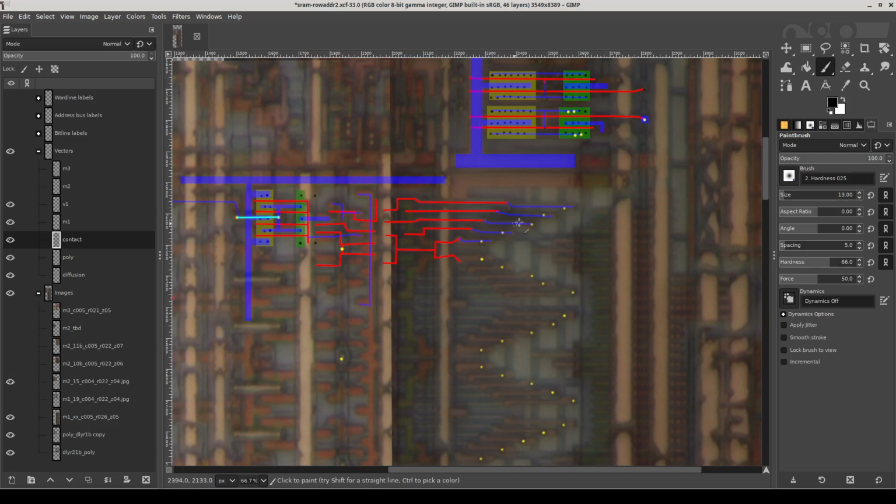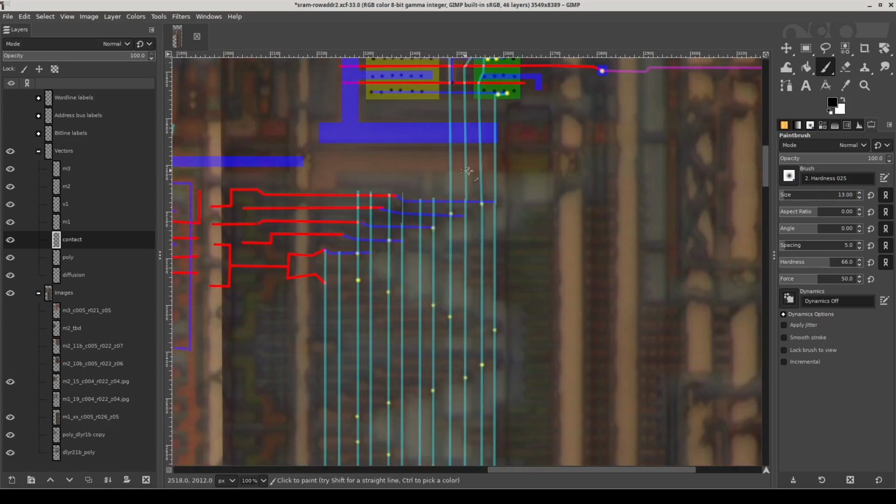We're not just going to be feeding in the raw address bus to here and then having a hardwired is equal to 0, is equal to 1, is equal to 2 circuit, because that would take up too much space. And of course, these vias are in different places, so there must be something fancy going on in the decoding here. So we can see the first couple of lines here seem to be paired, where there's exactly 1 via in each group of 2 of these vertical lines.